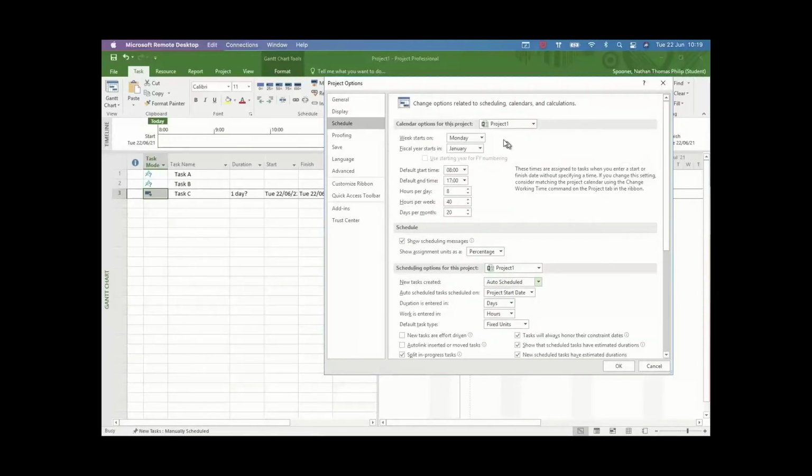So let's keep on this idea of these settings so far. In addition, the usual working day is obviously 8 till 5 with an hour off. However, your organisation may be working differently. So if we did a half 8 till 5 with half an hour off, we just have to change the settings accordingly to your organisation so it represents true working time. This is quite key when we're looking at percentage of work complete rather than percentage complete, which I'm sure my colleague Joe will follow up in a future session.